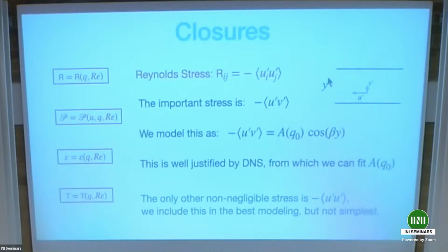And again, those people in wall-bounded and shear flow will hardly be surprised to learn that the only important stress is the U prime V prime stress. That's always the important stress in wall-bounded and shear flows. Again, hardly surprising. I could have told you that before I even started this. And again, we'll just expand it that way.